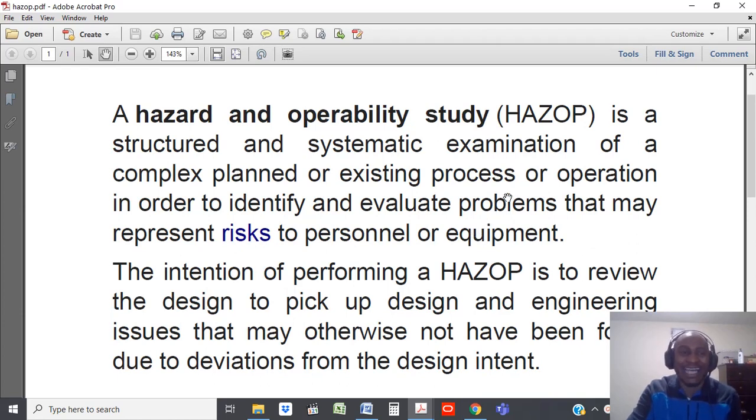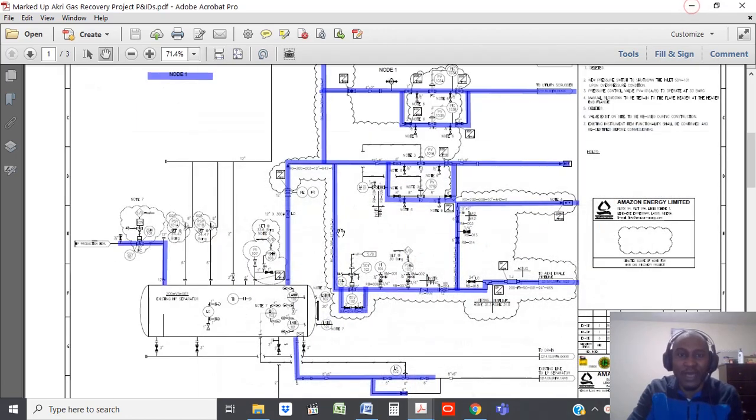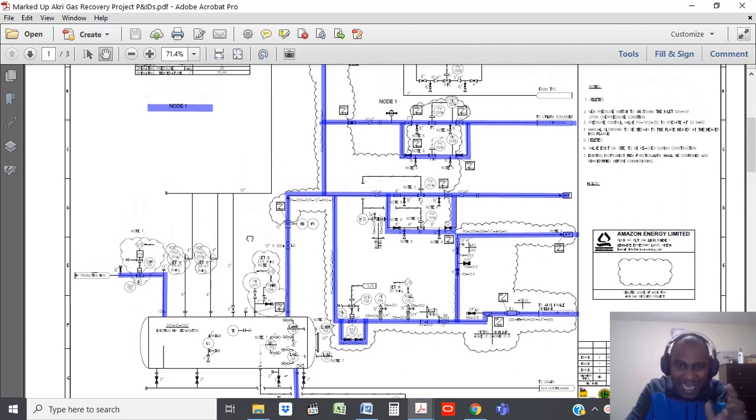When you're looking at it, we're not just looking at hazards. It's not like a hazard identification process in full. It's looking at the hazards that come out of operations, when you're opening a valve or closing a valve or doing some maintenance work. It highlights those issues so that you know what could come up when this system is in operation.